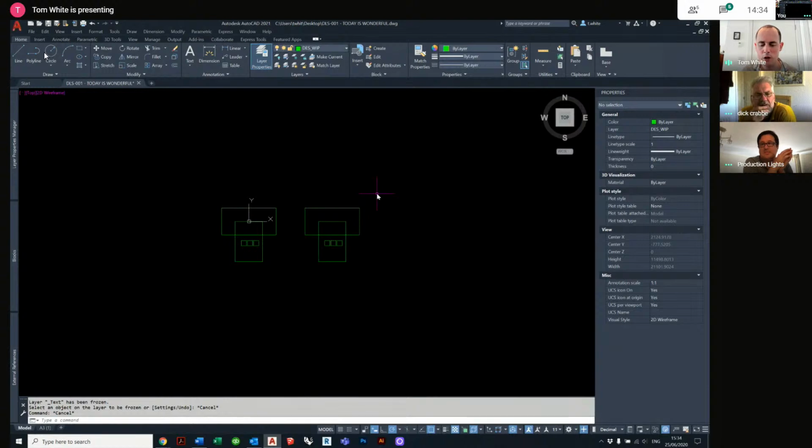A filter comes in when you have a drawing which has been changed from a PDF to a DWG using the automatic program, where you receive a DWG which is exported from Vectorworks, where you have a DWG which is drawn in a manner which might not necessarily be ideal, and you need to select a few objects out of it and do exactly what we talked about and say, select the hatch and put it on the hatch layer, select the solid and put it on the solid layer. That's how I'd use the filter command.